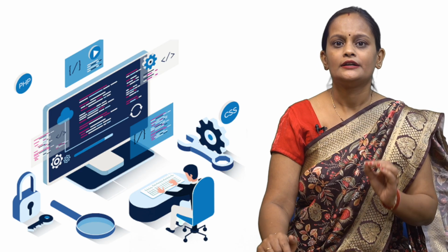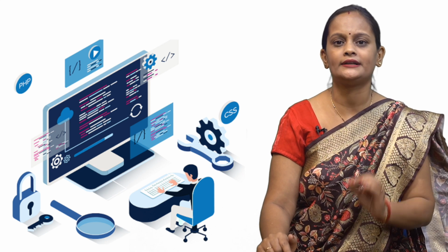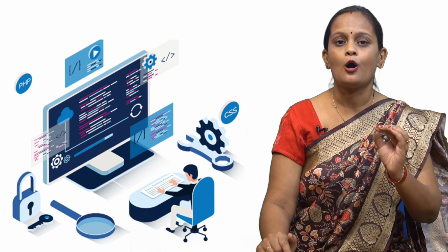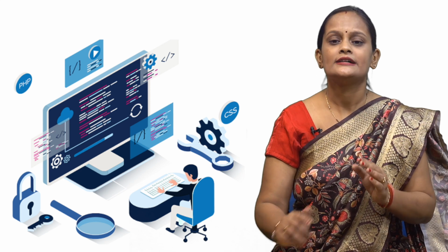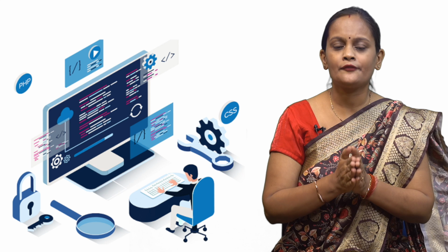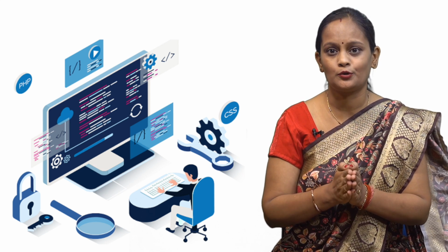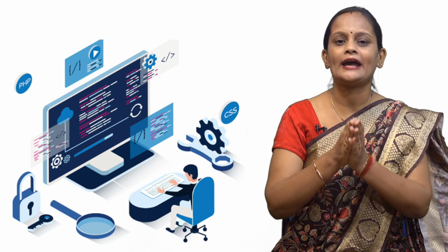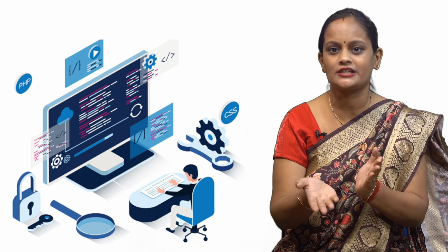This means if there are two or three switches having the same address and you give input to any one of the switches, all the rest of the switches will change their state. Generally, if it is a normally open switch and you give a high input, or 1, then it will toggle its state, or change its state.